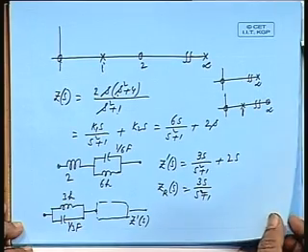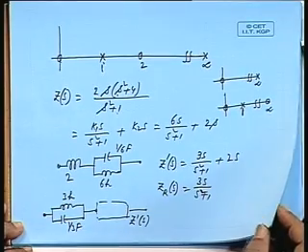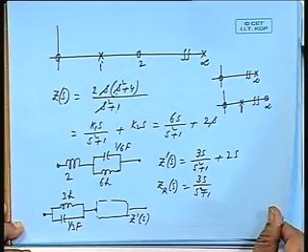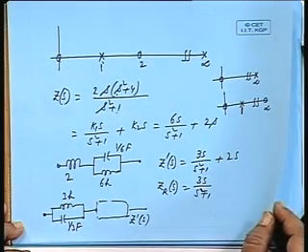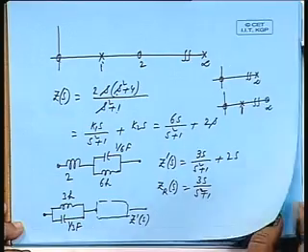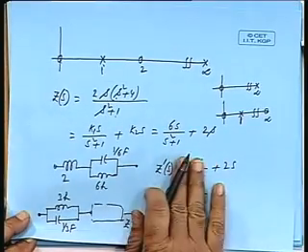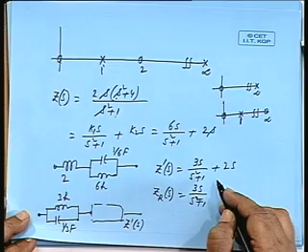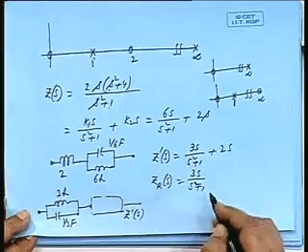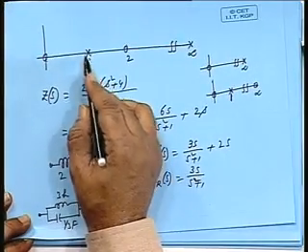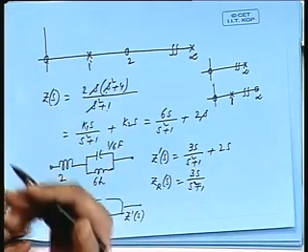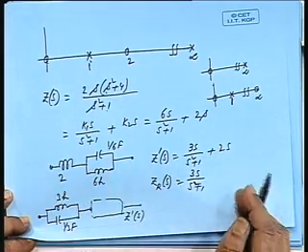What will be the poles and zeros of this? Poles will remain the same. I have not disturbed the pole. What about zeros? Now, this is not totally removed, it will have a new 0, all right. What I have done is, I have not totally removed this pole, I have weakened the pole, I have removed a part of that residue.